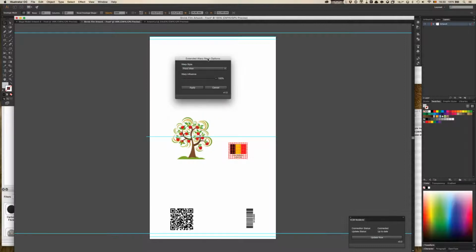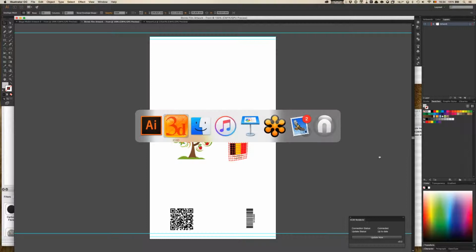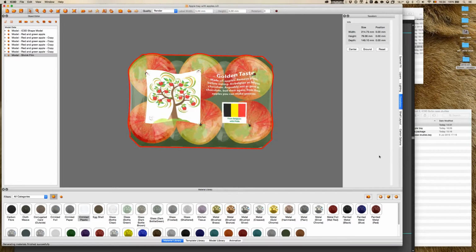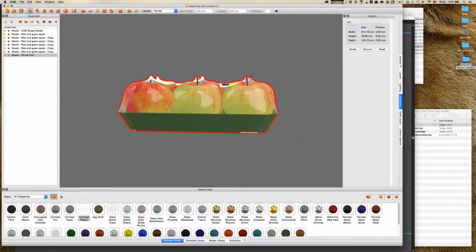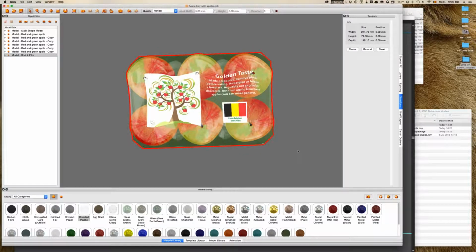This is the dialog that comes from iC3D Suite that lets me choose which methods, and I'm going to go for front view here, and then I'm going to do apply, and you can see that it does all kinds of weird things to my design. And if I go update and go back to here, you can see that it jumps to something that is actually pretty straight in this case.